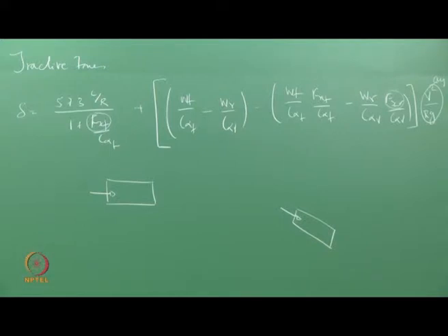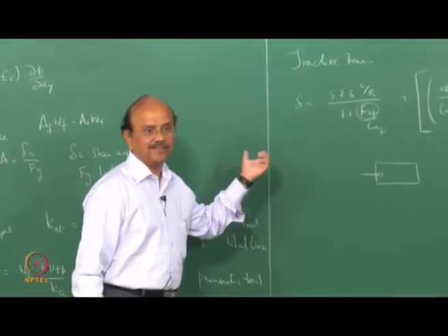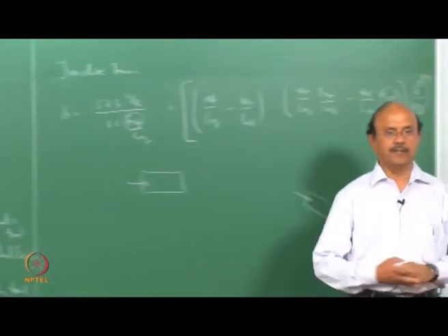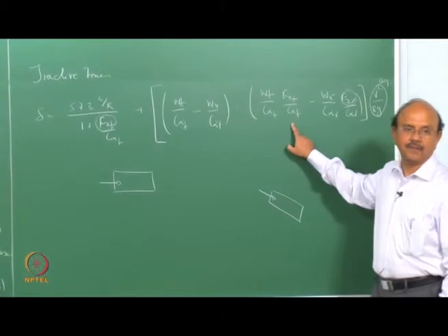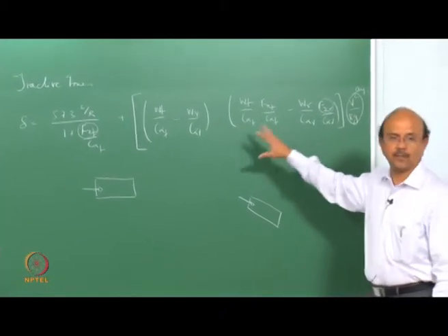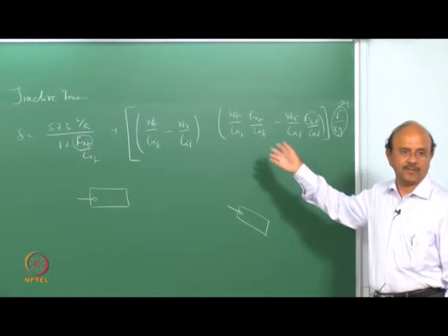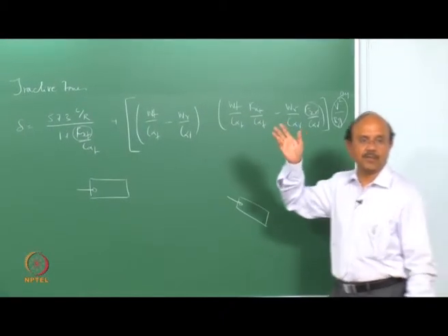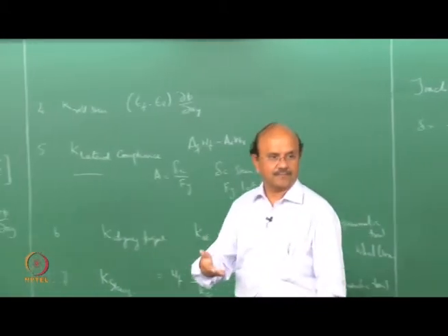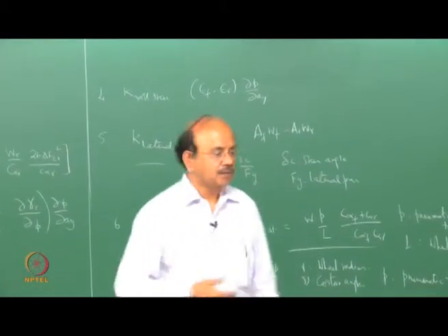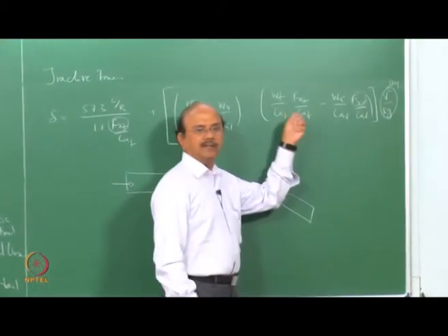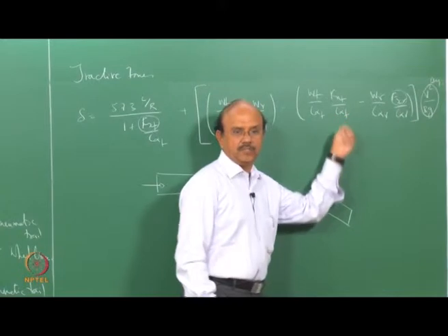Oversteer, because you have to give more delta to it. You will understand this in every term here. For example, if you look at this term, there is a minus, so it becomes an oversteer quantity. Delta is less, which means that it is oversteer. Delta is less here because there is a minus term here. The car tends to oversteer.